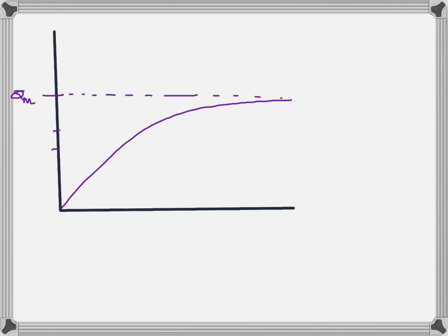So if you draw a graph showing charge on the y-axis and time on the x-axis, you're going to get an exponential graph that goes closer and closer to the maximum, as you can see, but doesn't touch it until after infinite time. And I'm trying to show where the time constant is. I'm trying to show that this point is almost where 0.63 of maximum is. If you watch closely, you can see that. It should be more than 50%, isn't it? 0.63, 63. So that is the time. Remember, this is the time axis. And so that is the time after which it reaches that charge. It's an exponential charging.